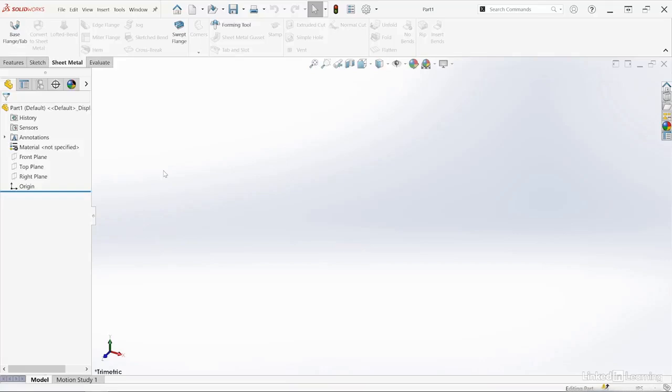So anything you design inside of SolidWorks has to start on one of those planes. So the general rules are you need to choose a face or plane to start drawing a sketch. Then we're going to take that sketch and we're going to extrude it, revolve it, sweep it, or something like that to turn it into a solid body. Well, when you are first starting out, there's really no other faces to work with, so you have to choose one of these planes. These are the fundamental planes to start with. Everything's going to start there, and I'm going to show you that in a second.